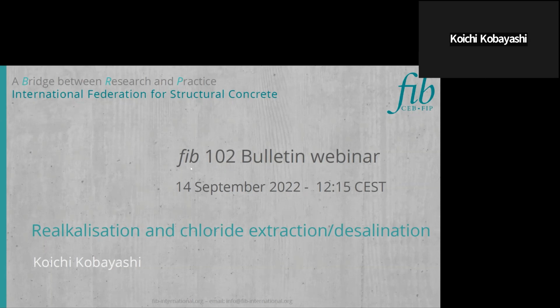So I recommend to apply a cathodic protection. I don't think that the chloride extraction can remove such a large amount of chloride. So for such a case, I recommend cathodic protection.